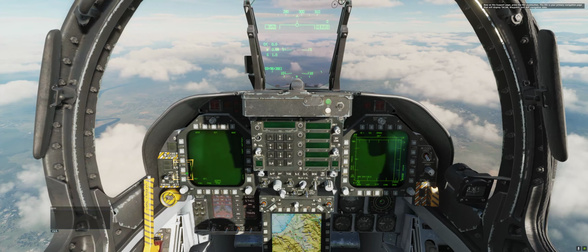In the center of the HSI is an aircraft symbol that represents your position from a top-down vantage. Your true airspeed is to the left of the symbol and ground speed to the right. Centered around the aircraft symbol is a compass rose, and on the very top is a lubber line that indicates your heading in regards to the compass rose. Along the top of the HSI is the SCL, or scale, push button. Consecutive presses of this push button will cycle through the scale range options of the HSI.